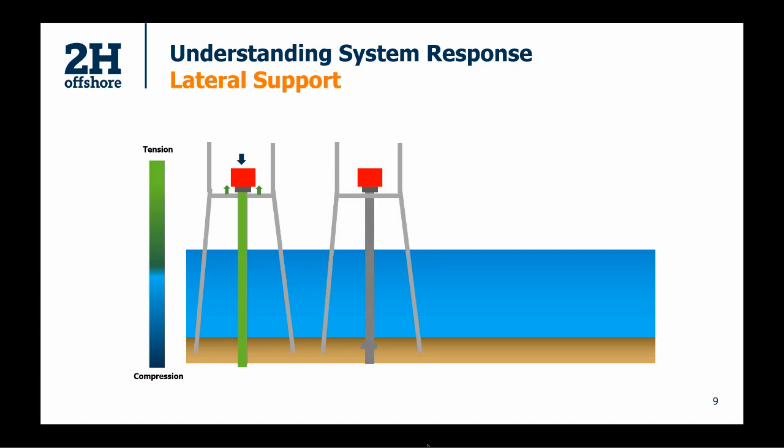If you have a well like this, where you're looking at a tieback well, so you've got a subsea wellhead here, you're still going to have compression in your conductor, but the compression levels aren't going to be too onerous because the weight of the casings from the subsea wellhead down will be hung off at this location. So we're only really looking at the weight of the casing strings from the subsea wellhead to the surface wellhead.